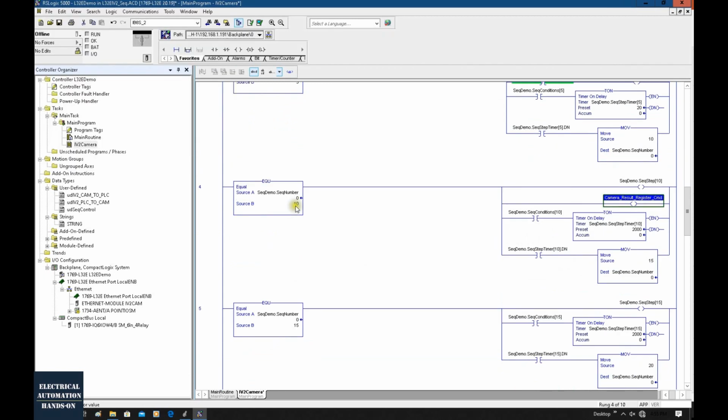Okay, and at step 10, we basically need to wait for one entire cycle in the PLC, and this register signal will be used as a command signal to register the camera results. So here, I will make it turn on for, for example, 15 milliseconds. Make sure it turns on for one entire cycle.